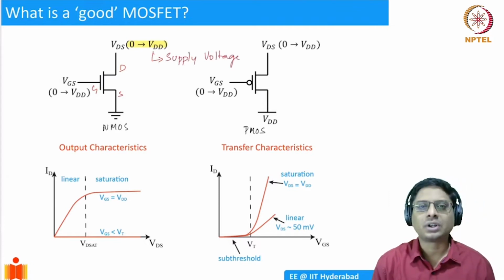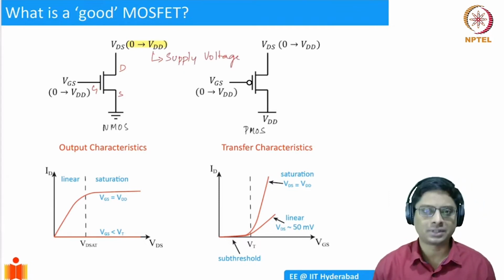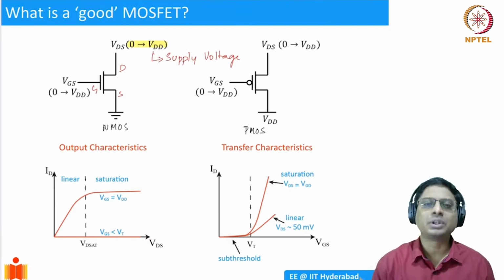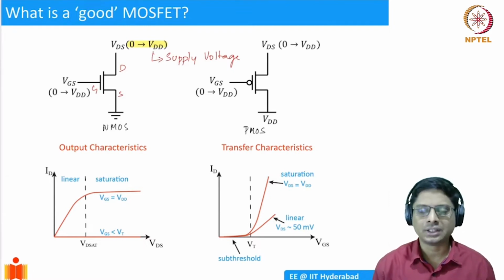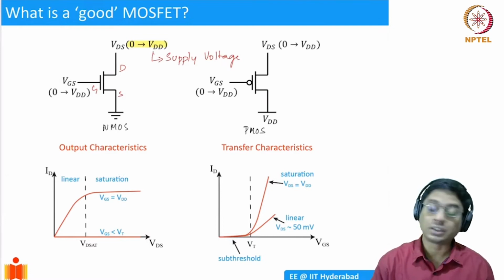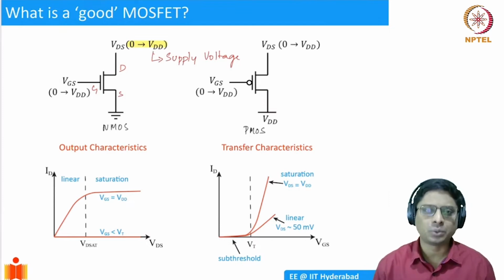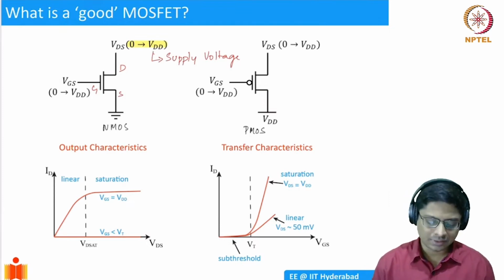Each technology can have a different supply voltage. The maximum voltage, sort of, you could think of it like that. For example, in the old TTL logic, we used to have supply voltages of 5 volts. Then that came down to 3.3, 2.5, 1.8, and 1. So nowadays it's usually around 1 volt. We will explain why that happens in the next week.